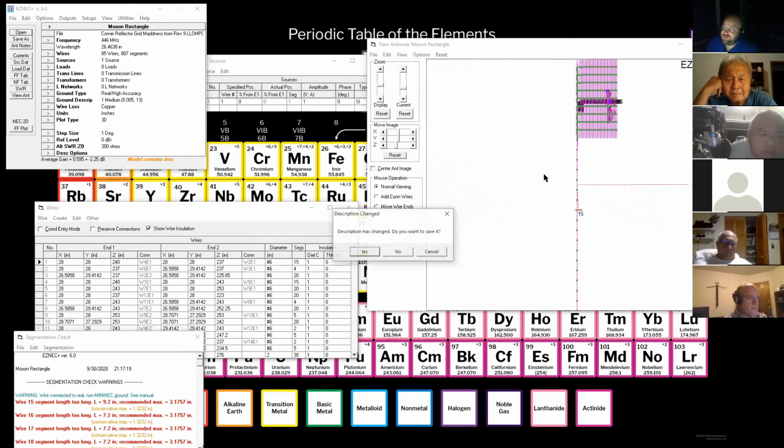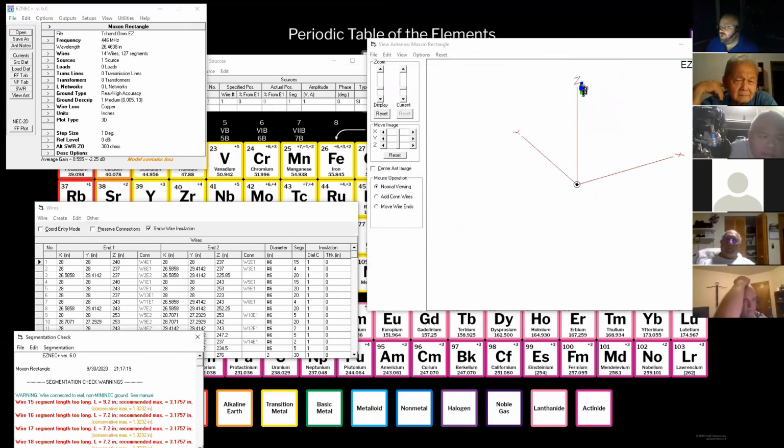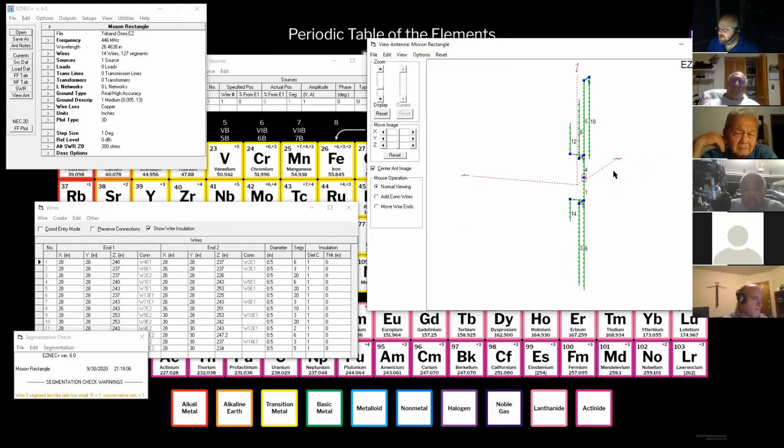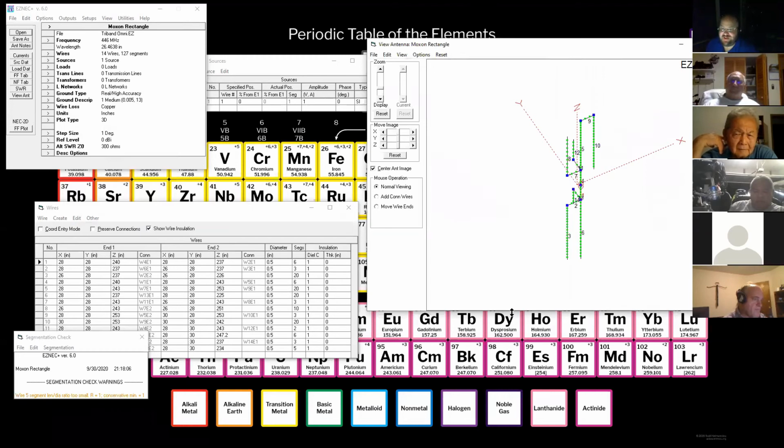So, and then if you're interested, this is what that thing looked like without the reflector on it. And that's why the pattern was so weird, is because at 220, it's using this element and this element, but these elements are also coming into play. These are the 70 center elements, and it's kind of pulling that thing off to the side on that one side. So I designed this because it did what I wanted it to do, and then I stuck it in front of that corner reflector to get the gain that I wanted.